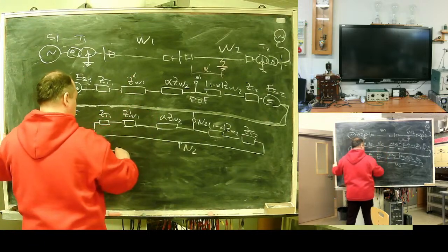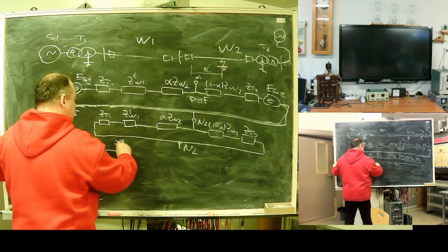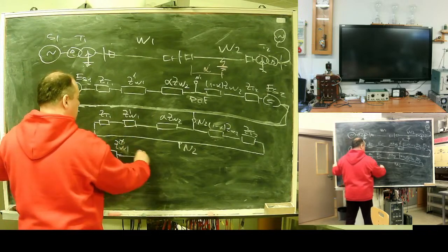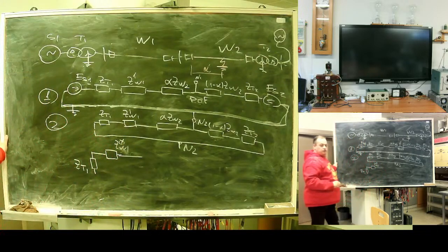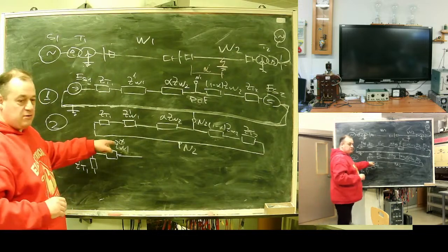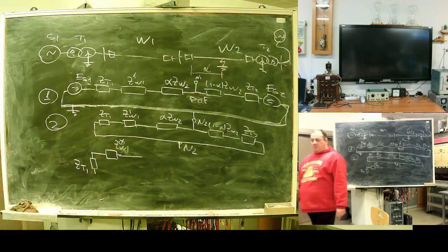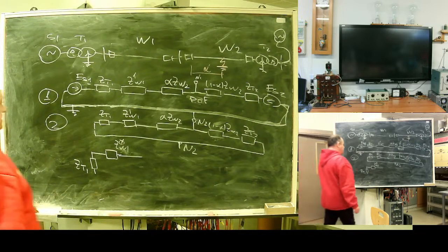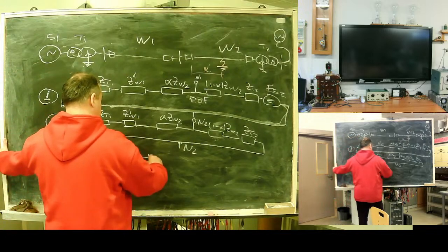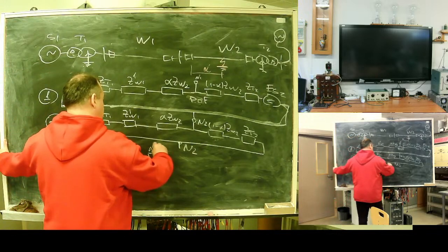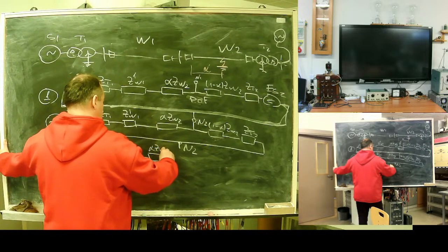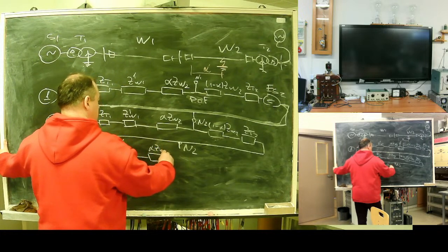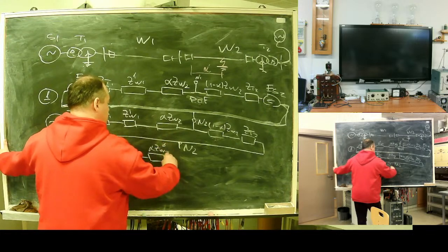Direct. Zero sequence resistance of the transformer, if not known exactly, is approximately 3 times higher than the zero sequence resistance of overhead line, approximately 3 times higher than the direct sequence. Zero sequence.